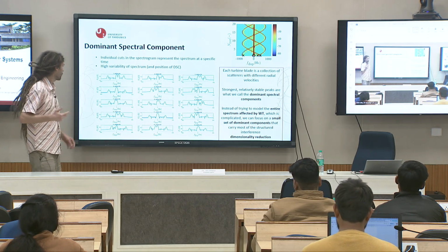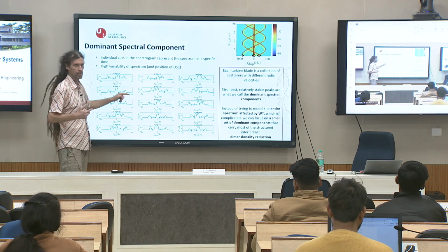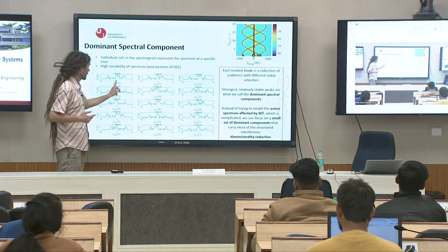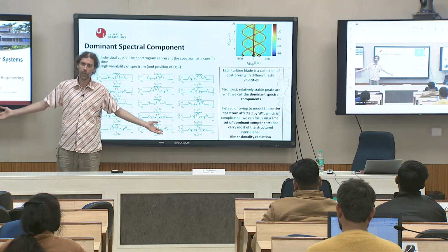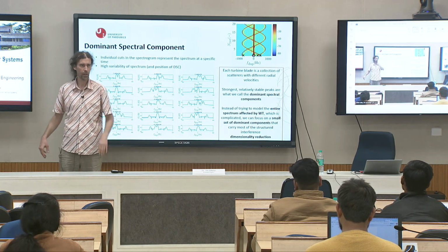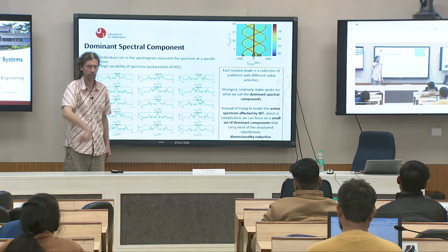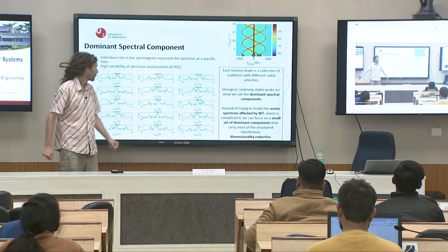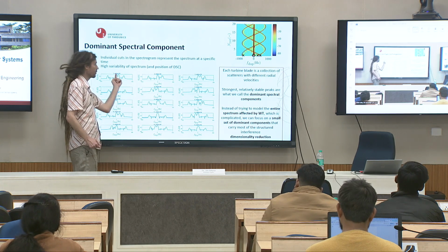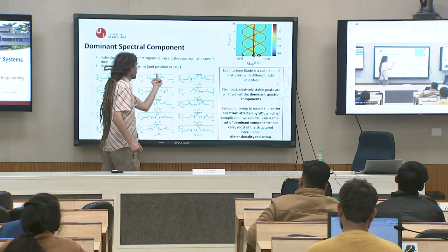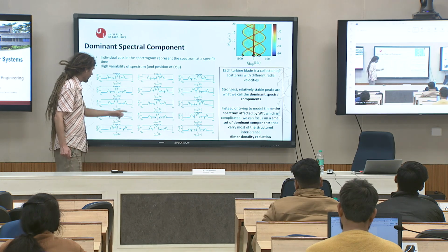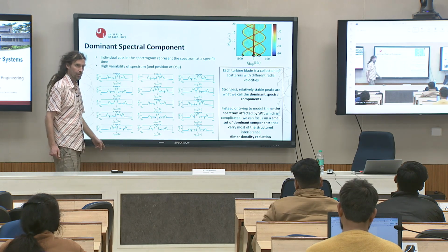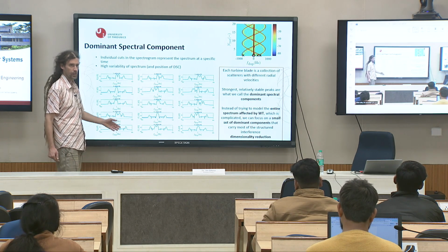Normally you should always see 3 maxima, plus at 0 Doppler you will see a stable maximum. What is it? The tower reflection at 0 Doppler. I don't care, the MTI filter is enough, it is static. So I can easily remove this one. But check the rest. Do you see any periodicity? No, not in the spectrum.